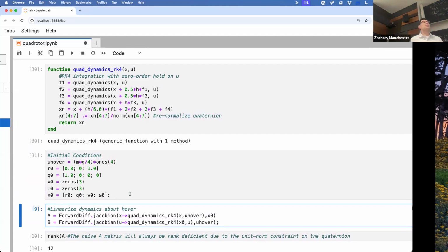Yes, exactly. So this is the identity quaternion, right? Scalar part 1, vector part 0. So it's cos theta for the scalar part, and cos 0 is 1. So the axis angle corresponding to this would be 0. It's just zero. That's the identity quaternion, right? And that will map to a zero axis angle. If it were the opposite convention, where positive Z is through the floor of the airplane or the drone, then this would actually be 180 degrees to make it upright. So that's just an FYI thing. You will see that if you do aero stuff, because that's a common convention.